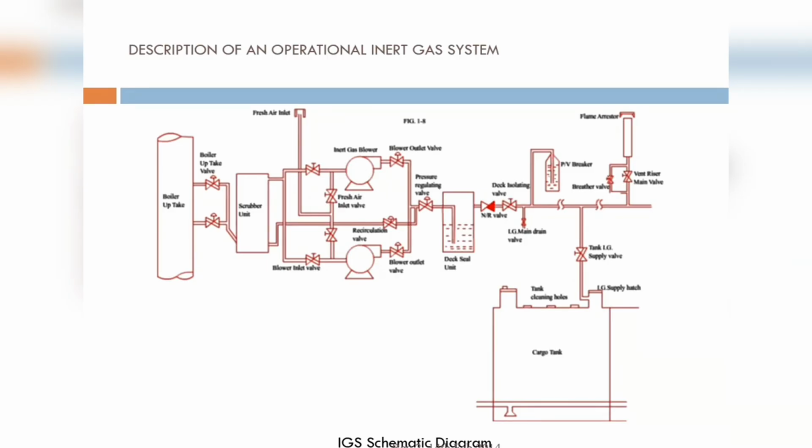But during loading, when you have a conventional venting system, venting through the riser in a conventional crude oil carrier and a product carrier, you don't leave it open, it will open on its own. You're not supposed to open it, keep it open and put a rope or something. Some people do it. It's not allowed. It will open at a set pressure, it will activate.